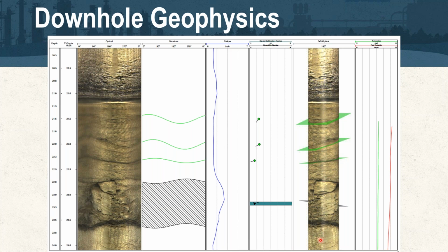And so kind of a similar parallel here that we want to highlight is, Derek can highlight with the pointer here, that the OTV is identifying a fairly broken up zone down below, roughly from 22 feet to 23.5 feet, that would indicate a zone of higher K and groundwater transport just based on the geophysical logs. Caliper indicates this as well. But what we also want to note is that the geophysical contractor did identify some low angle bedding features directly above that could be contributors as well.